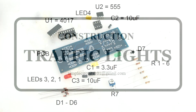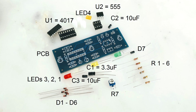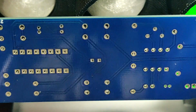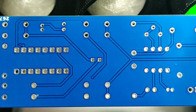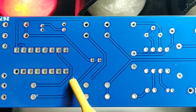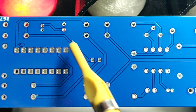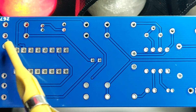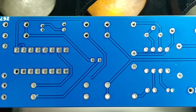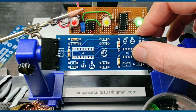Construction. This is the PCB and the various components used in the project. This is a style of construction which etches only a small portion of copper away, leaving most of the copper still attached to the PCB. I'm not a fan of this type of construction. I found the mass of copper left on the PCB acts as an effective heat sink and makes soldering very difficult.